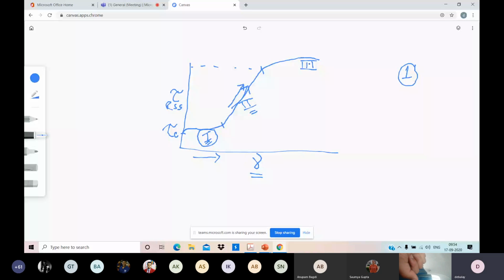Then a stage will come when stress becomes so high that cross slip occurs. Cross slip leads to dynamic recovery. That means now dislocations will rearrange and relatively come to a stable configuration, annihilate, rearrange, so that subsequently you will again find the rate of hardening decreasing. Here the rate of hardening is lower. Here the rate of hardening is very high. Here the rate of hardening was very low. That's why easy glide, linear hardening,